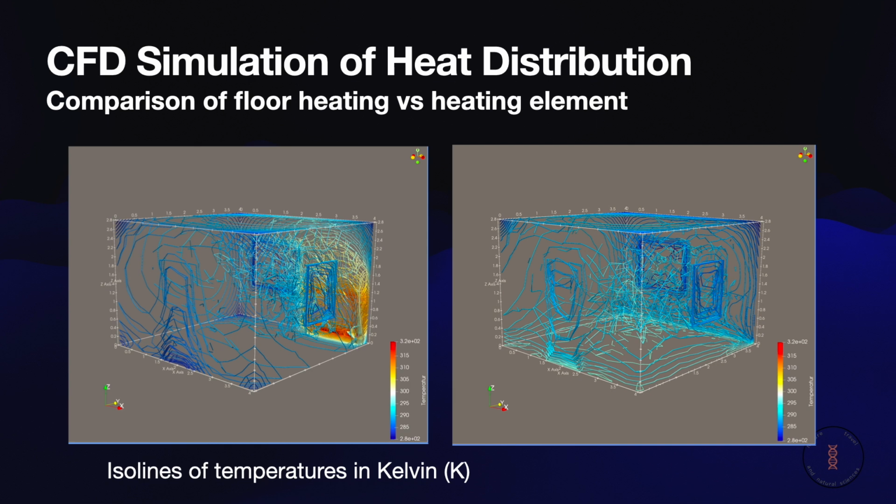Underfloor heating. On the right, the distribution is much more homogeneous. With a surface temperature of 25 degrees Celsius, we observe a steady vertical temperature gradient, where the lower part of the room remains warmer than the upper section, the inverse of the radiator profile.